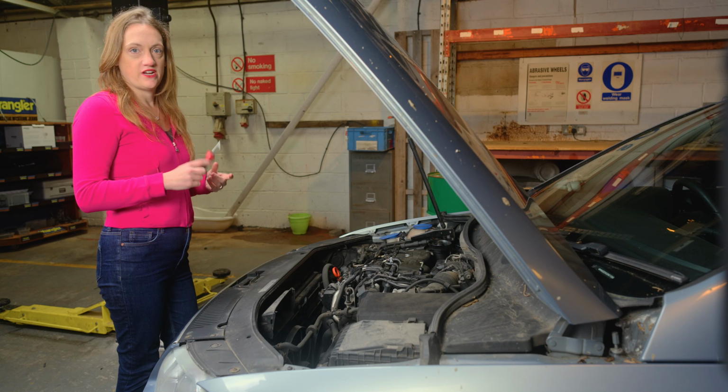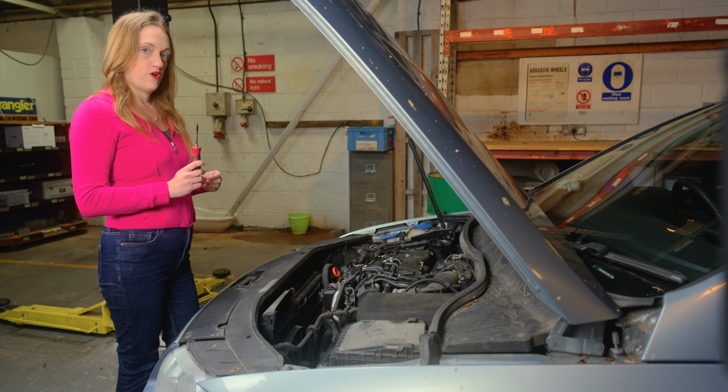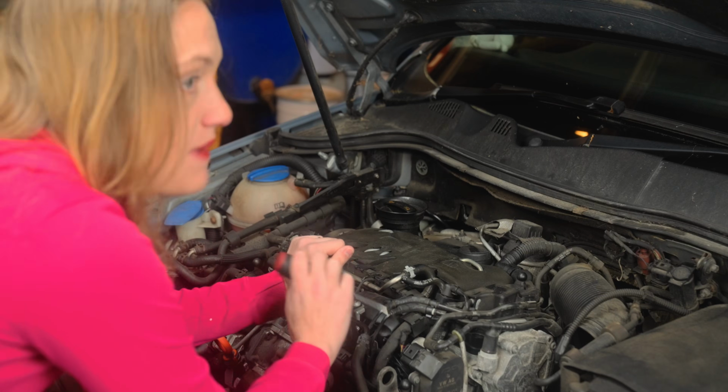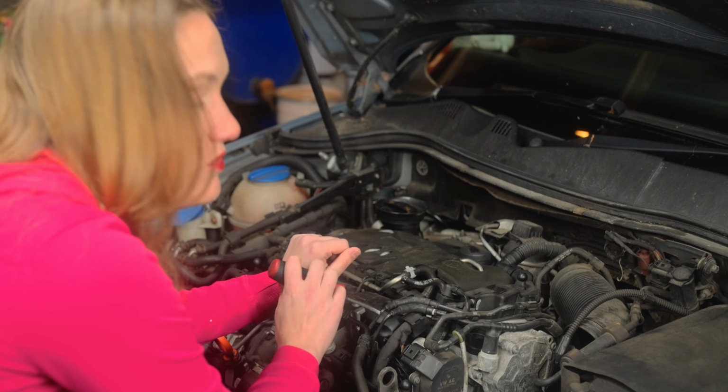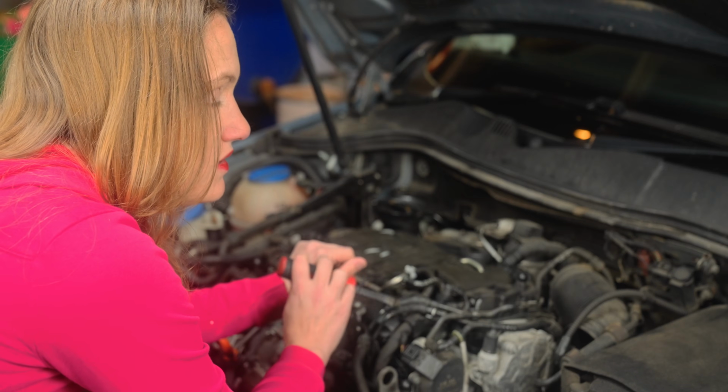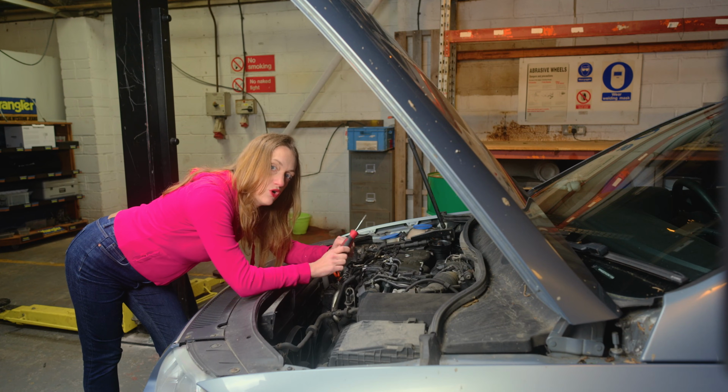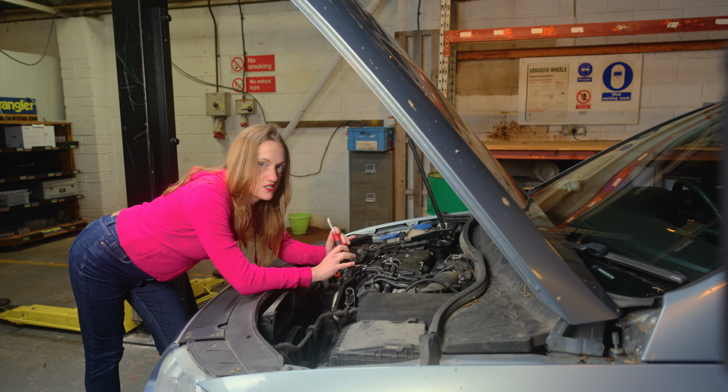We're on our A of our ABCs, which is check the wiring. I'm going to check that there's power and earth and that none of the wires are really obviously broken. Now our fault code says range performance, not open circuit, so that does suggest the wires are okay.